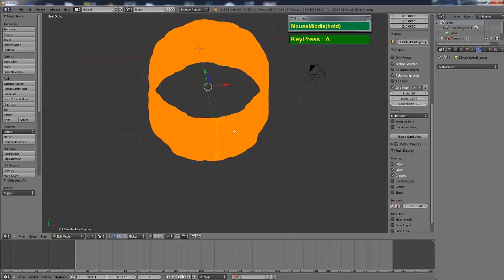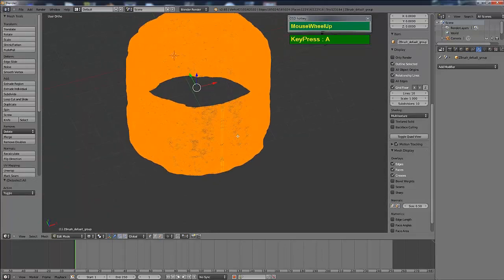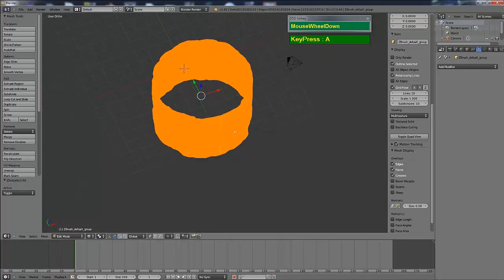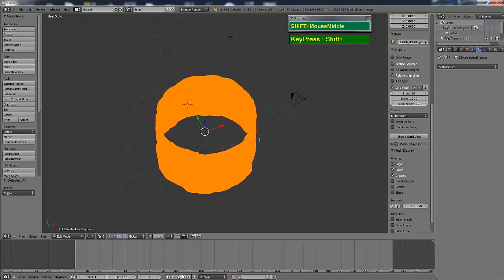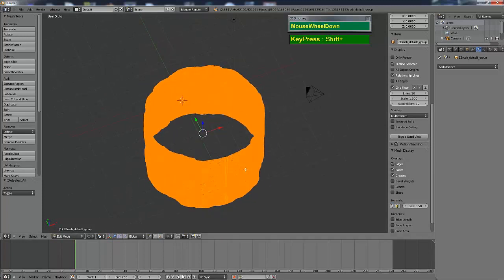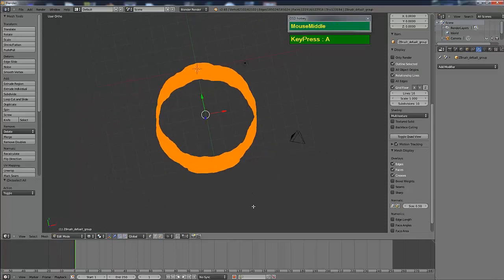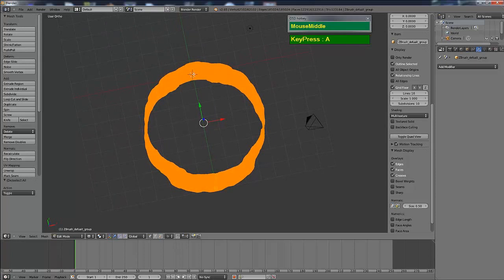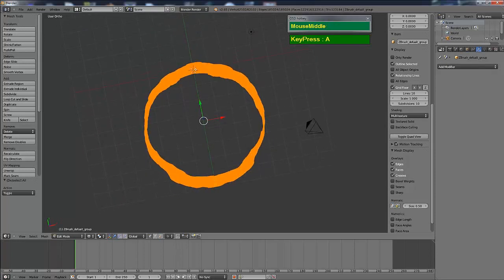Alright, we need to create a circular base for this container. Before we do that, we need to thicken it, so I'm going to duplicate another piece. Before that, you notice that my center is still at the origin. I need to move the origin of this object to the center.